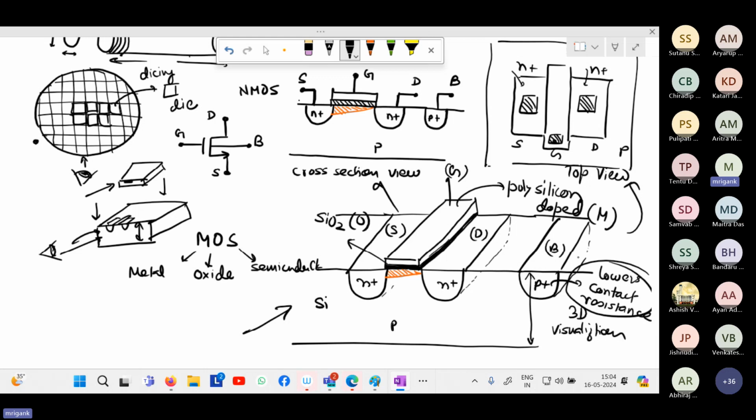But for the time being, you should remember that directly contacting the silicon with metal will create a Schottky junction. It will create higher contact resistance. We therefore apply a highly doped region. We select a pocket where we heavily dope that silicon and then connect with the metal. So for a P-type substrate, we have a P plus junction, and then we apply the metal, right? We are not applying an N plus junction because again, it will form a diode, right? The substrate is P. So P to P plus, and then go to metal. That will have reduced contact resistance.